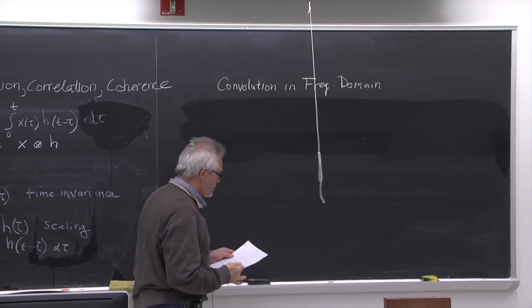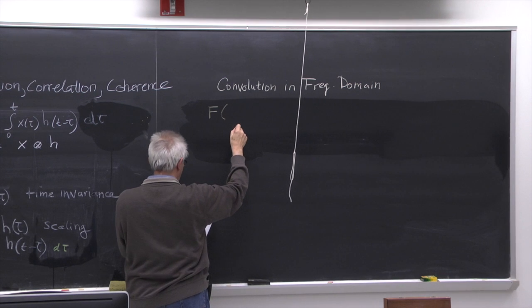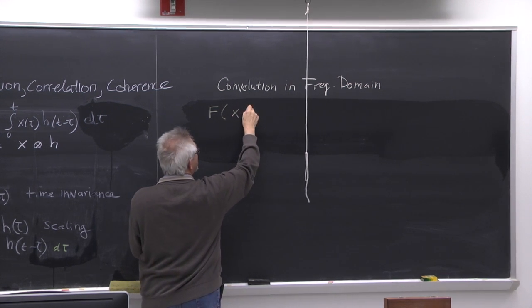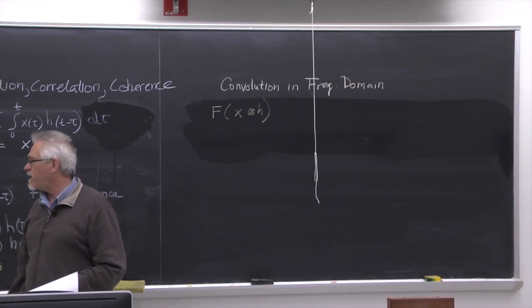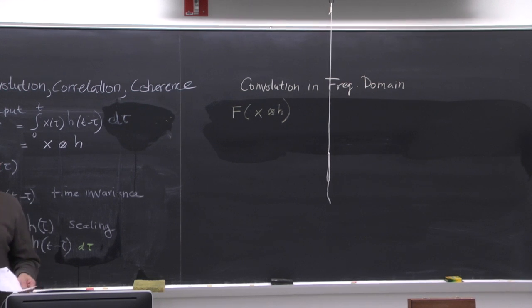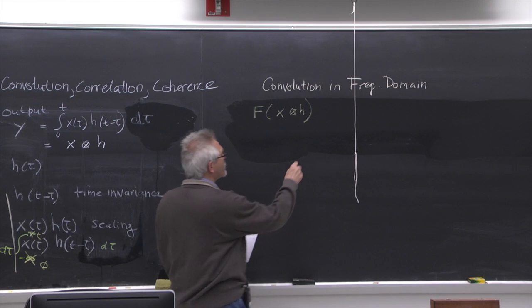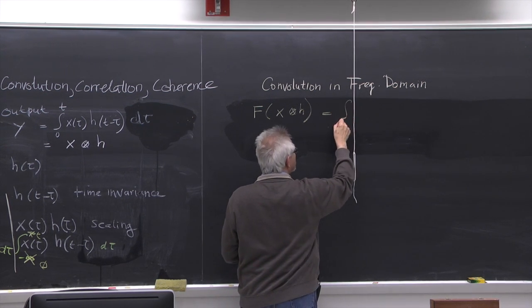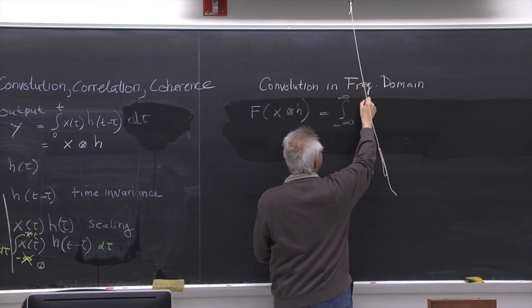How do we do that? We basically say, well, we take the Fourier transform of the convolution of two functions. Let's just take x times h. We just had that, so let's take that one. I think in the book I do x1 and x2, but that doesn't really matter. So now we apply the Fourier transform to the convolution.